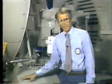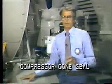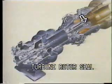Increased oil tank pressure, increased oil consumption, and white smoke coming out of the turbine exhaust can also indicate a damaged seal. If you have checked the output shaft, compressor rotor forward, and compressor cone seals, and there are still signs of a damaged oil seal, then it must be the compressor rotor aft seal or the turbine rotor seal. Since the engine must be disassembled to replace either of these seals, no further diagnosis is necessary. Both seals should be replaced at the same time to save on future maintenance.